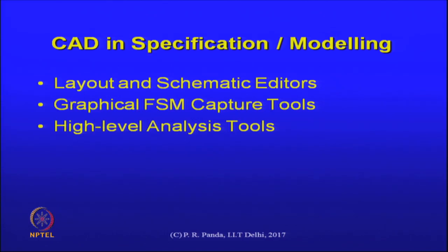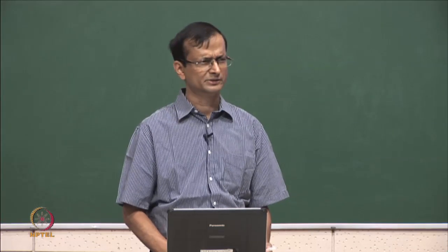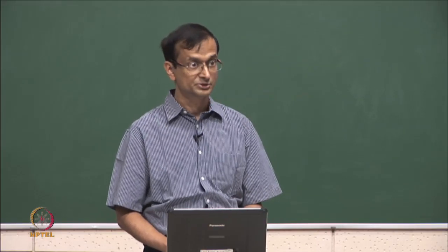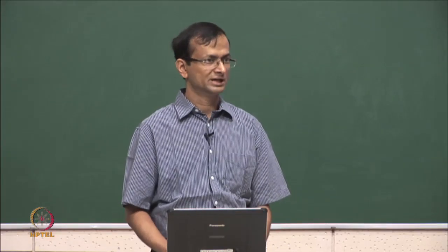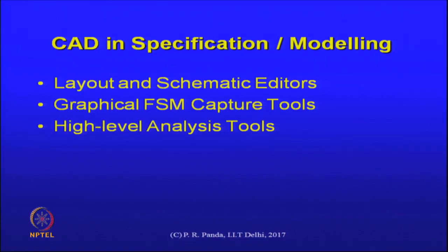Yes, a state table is a standard way of capturing a finite state machine. Both of them are equivalent, whether it is in diagrammatic form or a tabular form, the information is the same. And considering that these mechanisms are there for a designer to specify, you can think of tools to capture either that state table, or just a graphical tool for capturing the diagram. Capturing goes hand in hand with analysis. Once you have captured it, there is some high level analysis tool that you can build into that same framework.